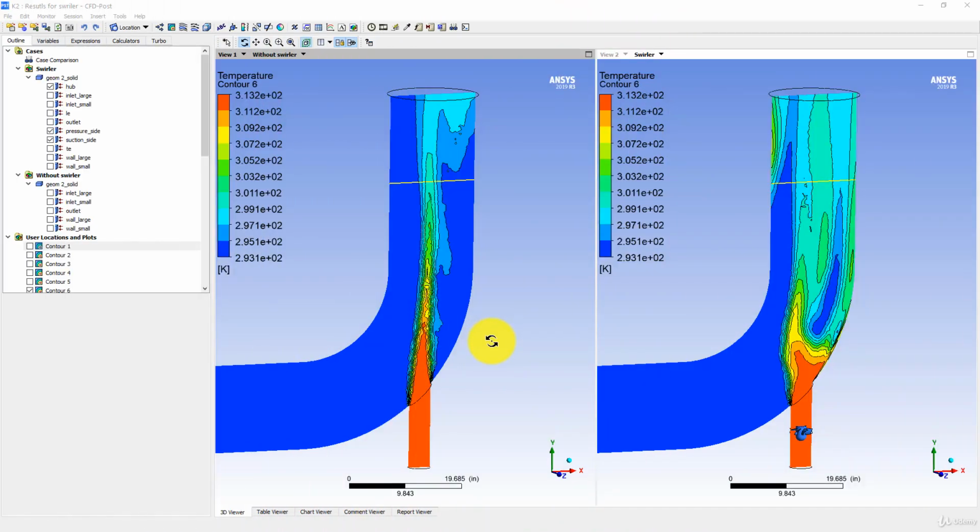In this workshop, we are going to study the effect of passive flow control techniques on the separation control in the mixing elbow. As you know, there are two types of separation control mechanism. The one is active control, in which we have control over when we want to turn on that controlling mechanism. For example, the jet flow from some holes, where we can control when we want to inject the flow through that hole, or we want to close that, that can be made automatic.